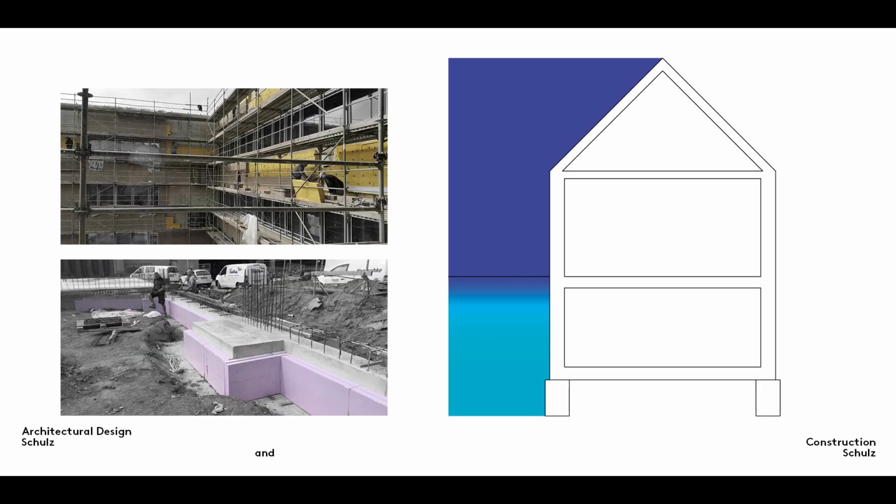In Northern Europe, the effect of winter cold on building shells is very significant, and shells must therefore provide heat insulation. Two different temperature levels meet at the base of a building because the external air around the building is colder than the ground temperature. At anything below 80 to 120 centimeters below the surface, temperatures remain above freezing point irrespective of the external air temperature, so that the thermal insulation characteristics demanded of the shell underground are lower.